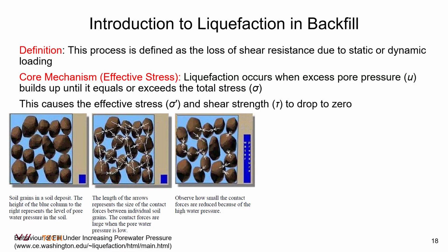why this liquefaction happens, we go back to the effective stress rule. Remember that strength comes from particles touching each other. But if the pore pressure rises too high, it pushes the particles apart. And so looking at the effective stress equation, when the pore water pressure rises, it causes a reduction in the effective stress. So let's look at behavior under increasing pore water pressure.